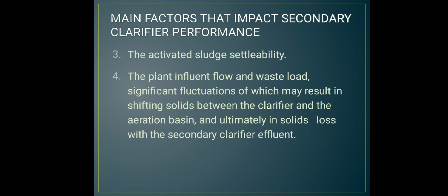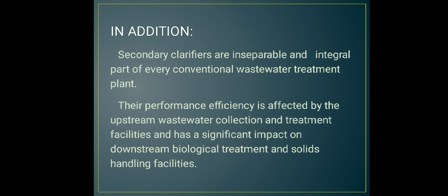The plant influent flow and waste load, significant fluctuations of which may result in shifting solids between the clarifier and the aeration basin, then ultimately in solids loss with the secondary clarifier effluent. In addition, secondary clarifiers are an inseparable and integral part of every conventional wastewater treatment plant. Their performance efficiency is affected by the upstream wastewater collection and treatment facilities and has a significant impact on downstream biological treatment and solids handling facilities.